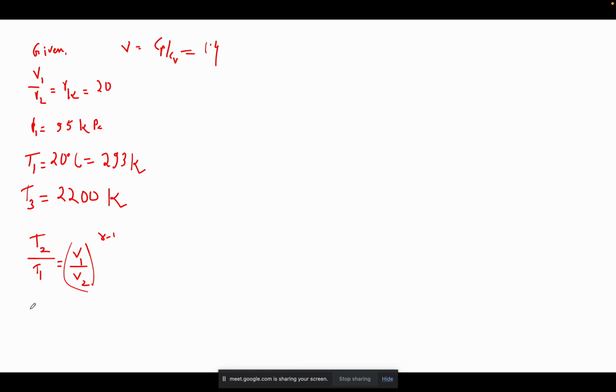Okay, so from here T2 will be nothing but 293 times 20 to the power 0.4. So that will be your 971.13 Kelvin. Okay, you got T2, you got T3, you got T1.